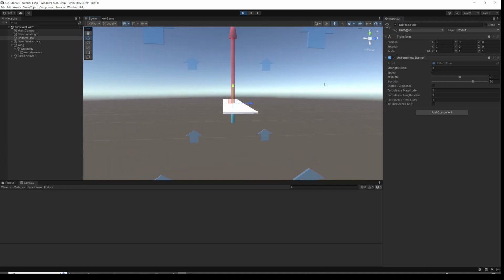It's just getting drag, no lift, but as I carry on, the wing is now effectively flying backwards, so the wind is coming from the trailing edge, but it's at a positive angle of attack on the trailing edge, and we're generating lift that way. So wings do work backwards. They're not quite as good as when they're working forwards, but they will produce some lift. Great, so let's set this to, say, 20 degrees angle of attack.